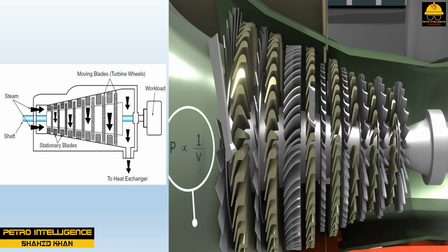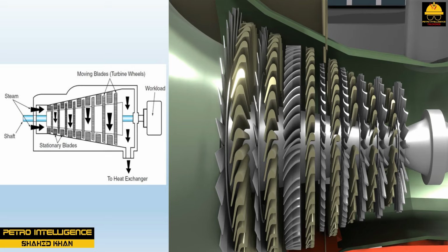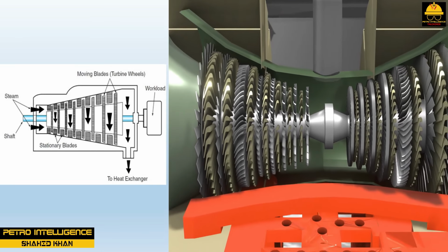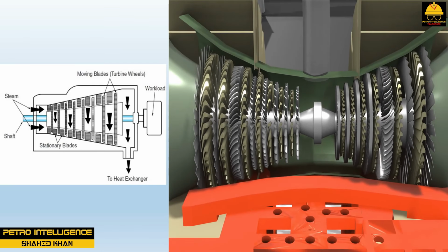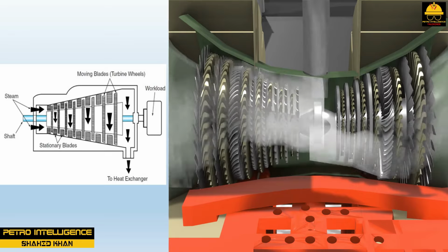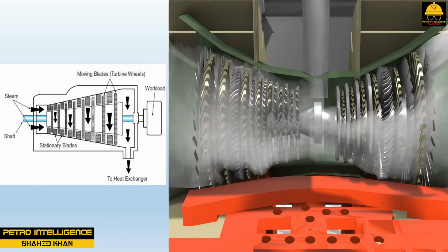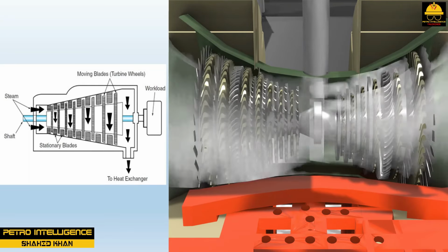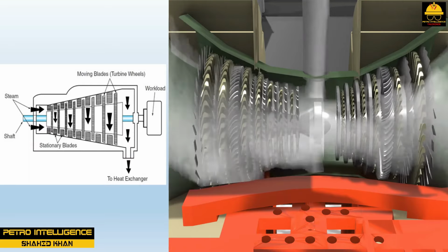The rotating paddle wheel is attached to a shaft, and the blading and shaft together make up the rotor. Impulse or reaction movement occurs as the steam strikes the rotor, converting the steam energy into mechanical energy. The amount of steam energy needed to perform useful work depends on the pressure range through which the steam expands.